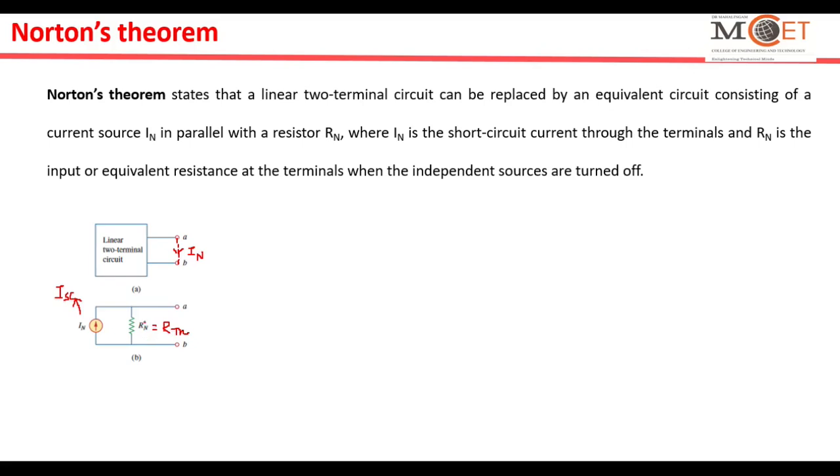How to find out Rn or RTH? It is a very similar procedure to what we followed in Thevenin's resistance. You have to look from this side and calculate the equivalent resistance of this entire network.